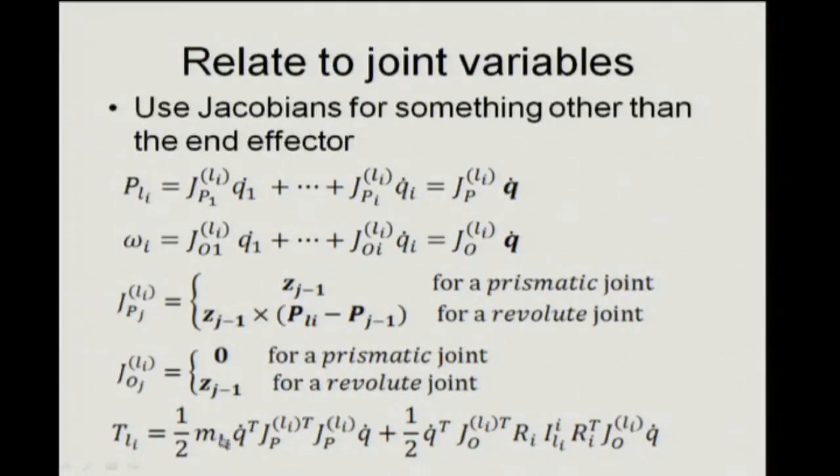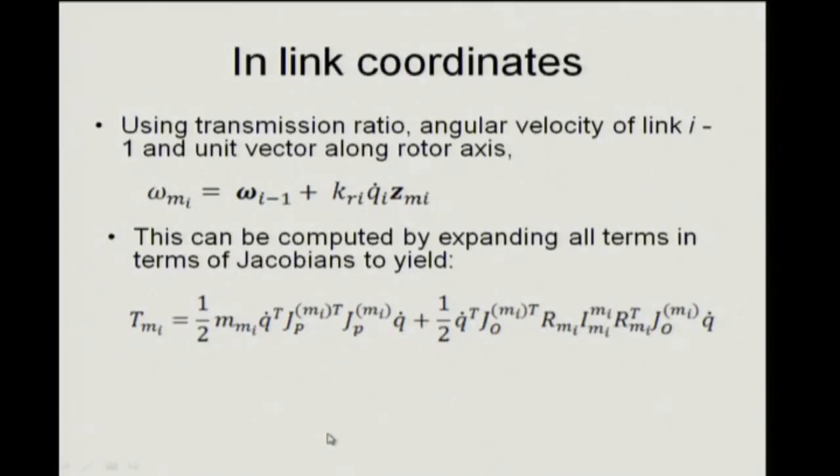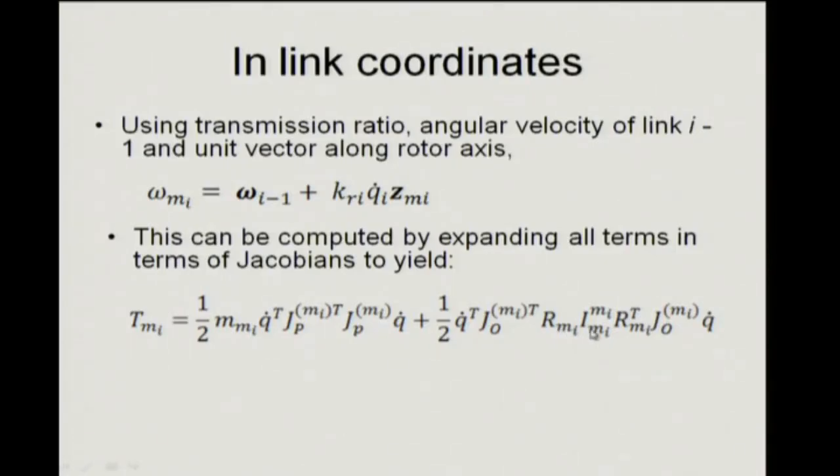So, this is one of them. The only thing is the relevant Jacobians are different. Okay. So, in that case, through the Jacobian we are trying to find the Jacobian which is relevant to find the velocity of the center of mass. In this case, we are trying to find the Jacobian which is relevant to the center of mass of the rotor. And the rotation matrices could be a little different, which is the rotation matrix of the link on which the rotor is situated.